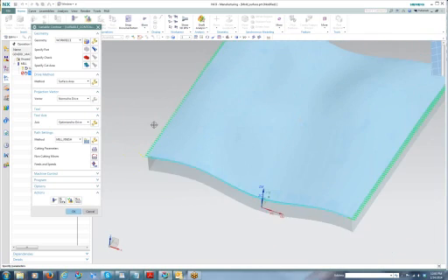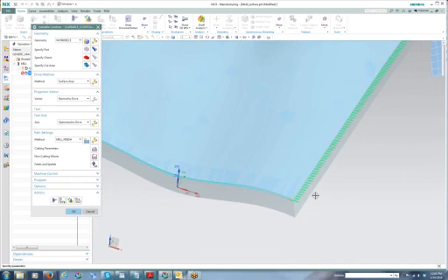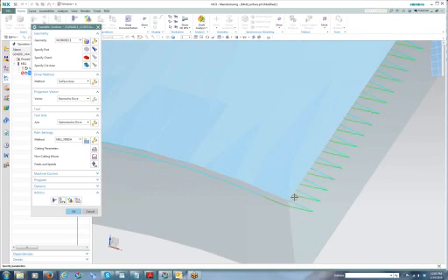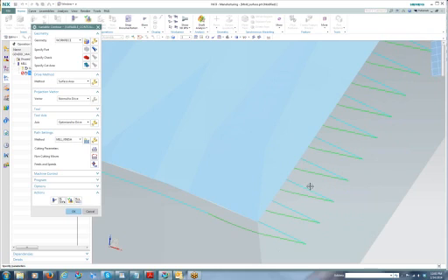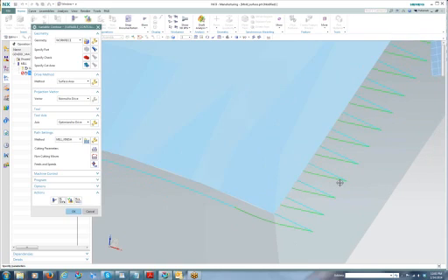On a large tool, these techniques can save a lot of time in machining. You'll minimize your air cutting, and you'll maximize the step over that you can use and still get the finish that you're looking for in your tool.